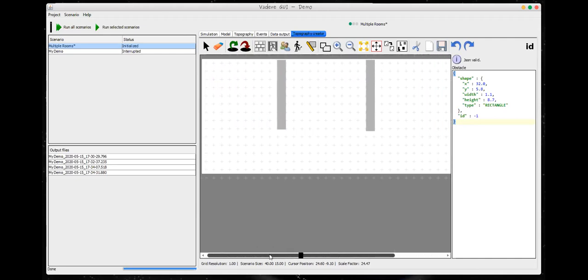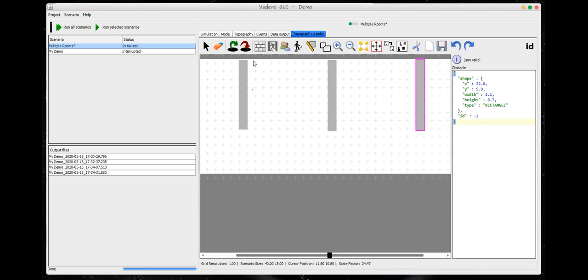So one of the things to note when you're designing these and dropping these walls in is that you do need to make sure that you don't have these little gaps in this space. It's interesting, if you do, then the simulants will try to go through those walls if they're part of that shortest path, and clearly we don't want that. So all right, I'm going to put those walls into this room.